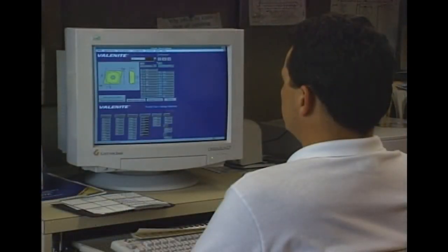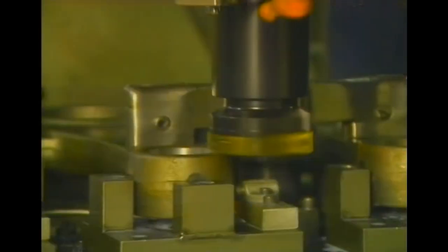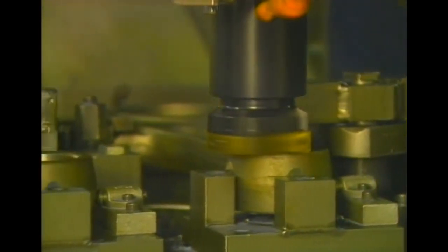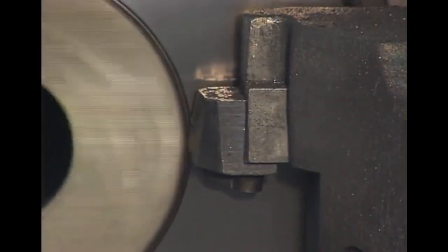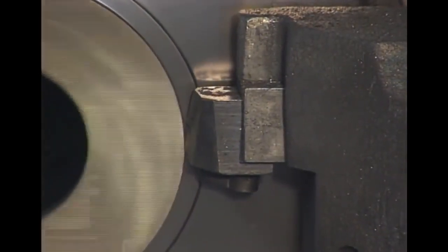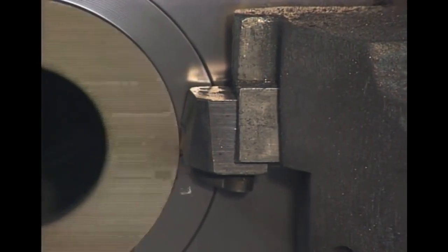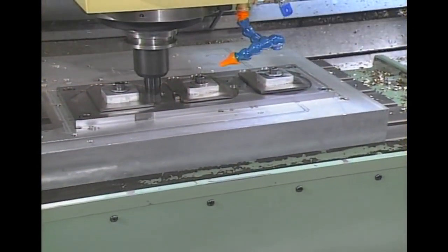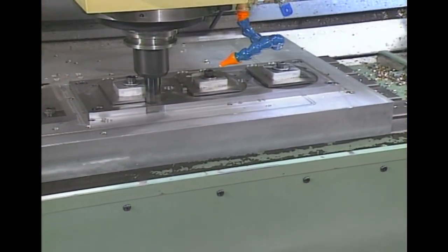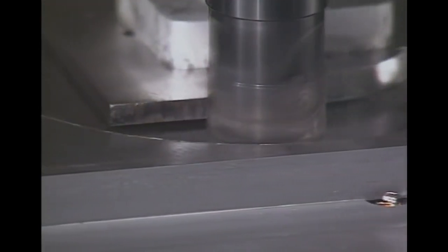There are many considerations when selecting a carbide grade for metal cutting, such as the type of workpiece material, especially its hardness, and the condition of the workpiece's outer skin. If it is a forged or cast workpiece, a tougher insert should be selected. Is the cut heavy, or is the cut light? Is the machine tool and work holding setup rigid or loose? If loose, then a stronger, more durable carbide grade should be selected.